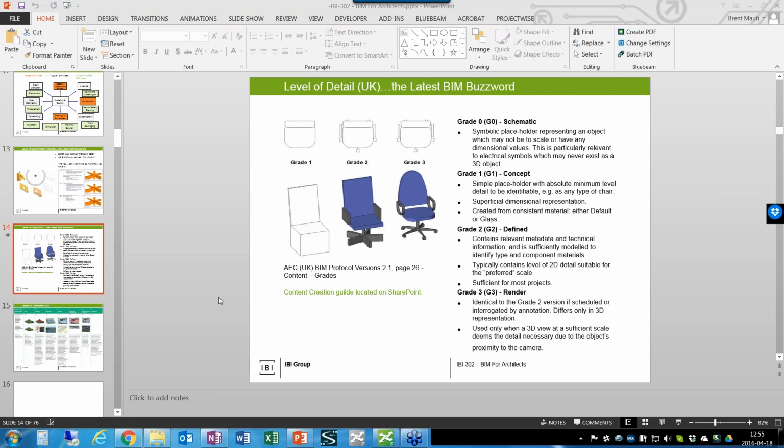But then we have to account. Well, I'm probably going to want to visualize it. And my client, if I'm giving it to somebody, they're not going to want to see that. They're going to want to see that. So it's a delicate line between what you model from a BIM perspective and then putting a little more detail for renderings, versus maybe I just leave it like this and I hand it to an advanced visualization specialist. And I say, look, every time you see this, not only do I want that, but maybe a little more detail. So maybe there's a mesh backing and they're going to do some advanced thing in 3D Studio. In my BIM model, all I need is that to show up on my plan. So that's something to think about.